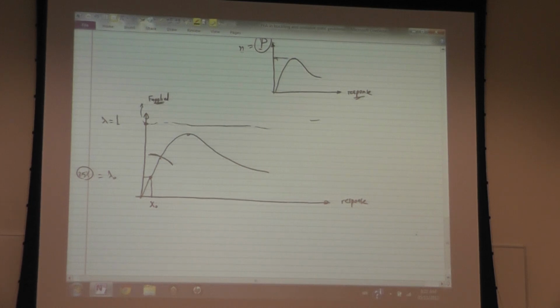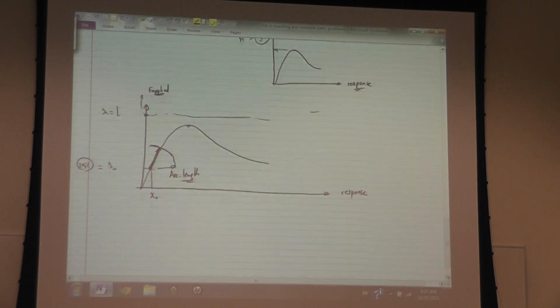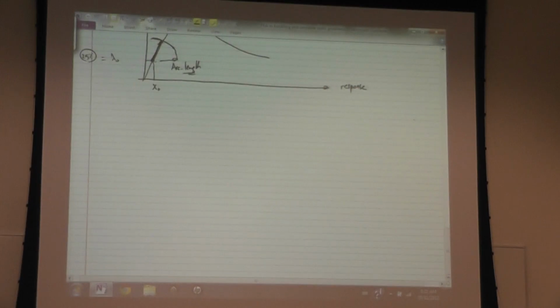So the applied load is another variable that can be obtained by restricting the increment on this load displacement curve, the length of that increment, and that's what we call the arc length, by restricting how much we can move on this curve. So, sum of forces equals 0, that's first, an equation in displacement variables.